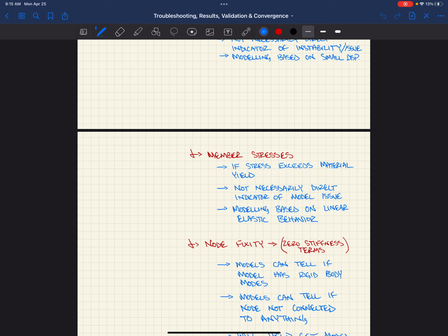All right. So for the, ma'am. I have a question. Yes. So for the results, there's a red for the status and then a yellow and then just the normal tan. Yep, it's color, just different levels. I'm pretty sure that the red is more based on the actual modeling analysis, like instability with the finite element portion of the analysis. I think the yellow is more on inaccuracies further down the road, in the design tab, when you're actually taking those things and designing them.